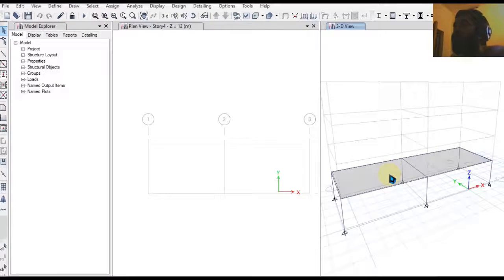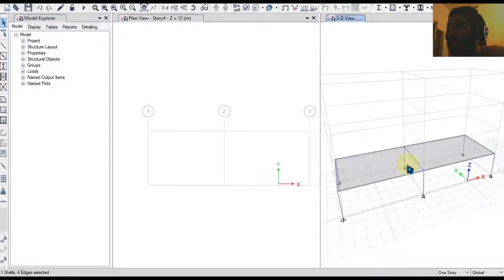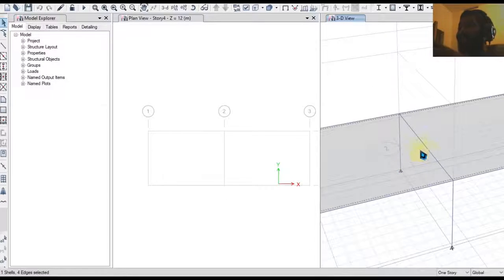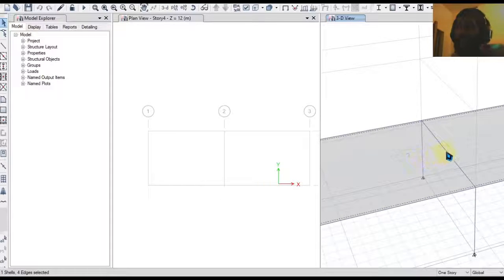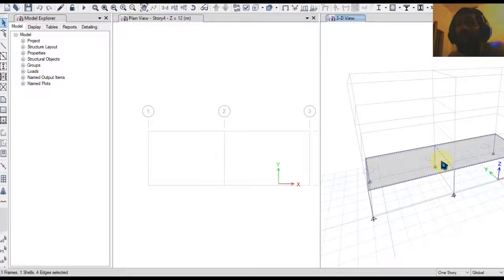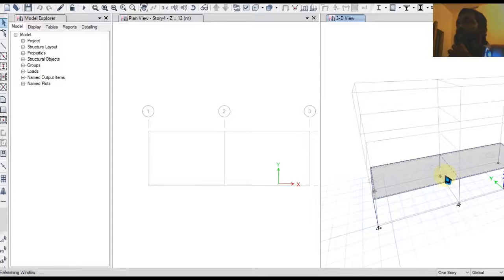Do you remember this thing which I've told? You can see that there's only a single shell right here, but in the actual case, if you would like to split these shells, you can just make use of this option. If these are 2 rooms, I'll recommend you to split up these shells. But if it's a single room separated by a beam, you don't want to do this thing that I'm about to do. The thing is, I'm gonna select the slab and the beam right there.